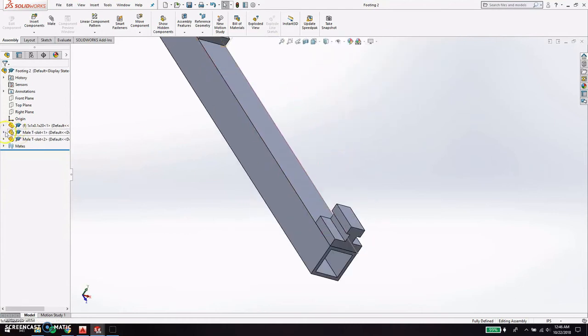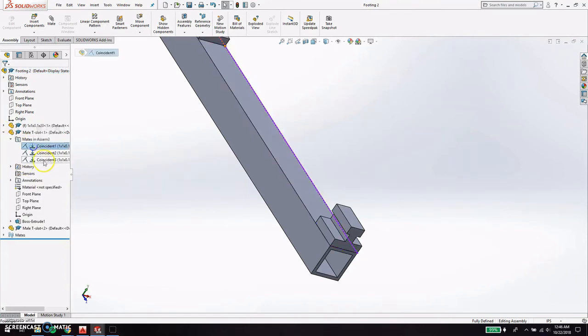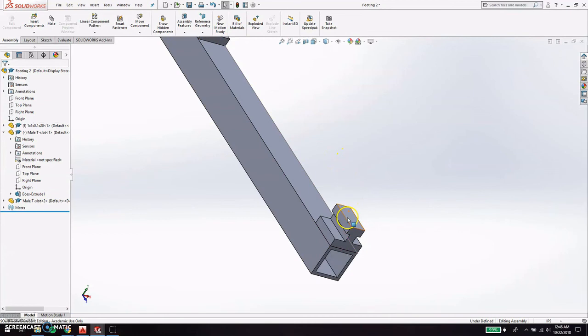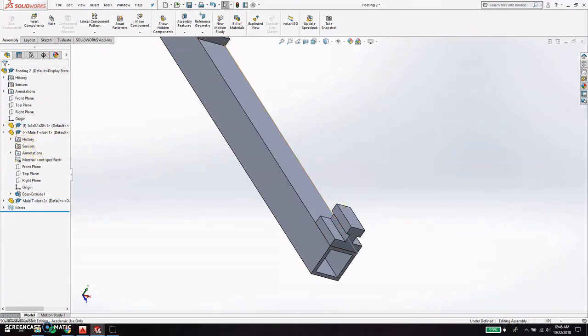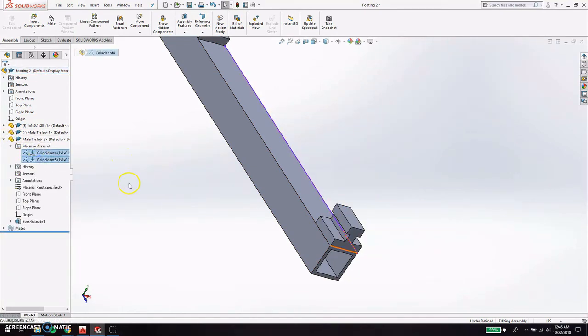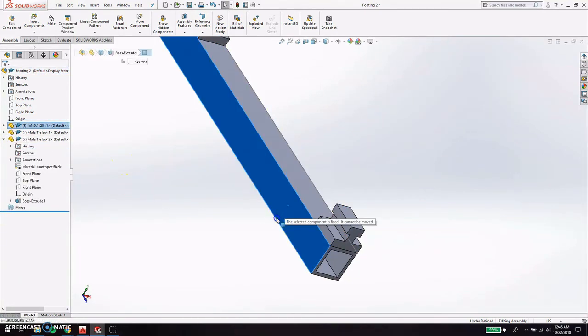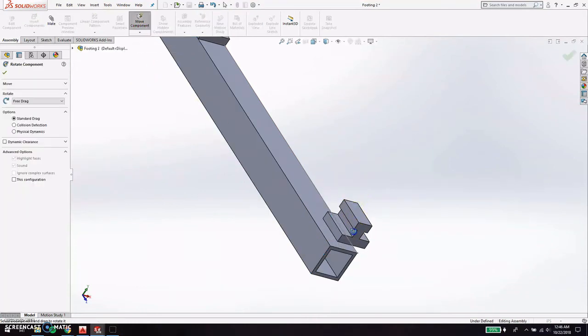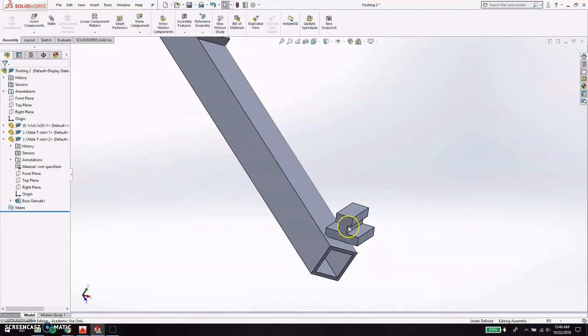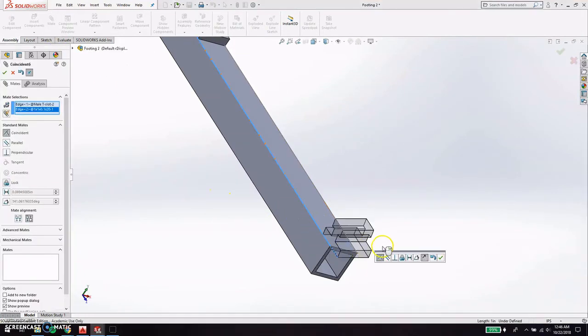So the way that we're going to do that is we're gonna remove the mates here, and we're just going to rotate them. Rotate these pieces around, and it'll be fine. So yeah, let's do that for both these slots. There we go. And something will move. Okay. So we'll take this and we'll rotate this just a little bit. And then we'll just mate this just like that.